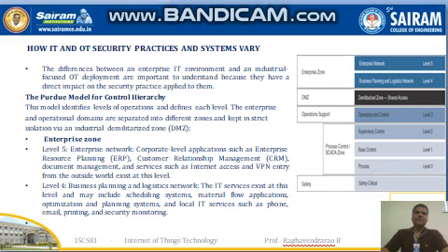The last one is the safety zone. Safety is critical, always. This level includes devices, sensors and other equipment used to manage the safety functions of the control system. One of the key advantages of designing an industrial network with structured levels, as with the Purdue model, is that it allows security to be correctly applied at each level and between the levels. That is the advantage of this.